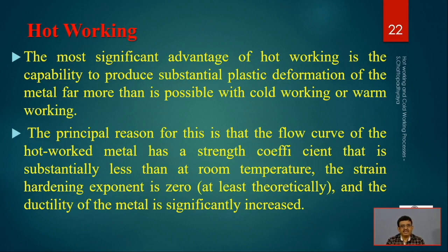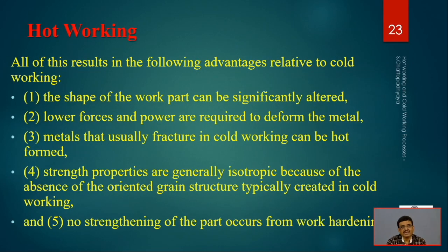And the principal reason for this is that the flow curve of the hot worked metal has a strength coefficient that is substantially less than at room temperature. Those things, K and n, have a role to play. The strain hardening exponent and those things are favorable, and the ductility of the metal is significantly enhanced, and that is why we are doing that.